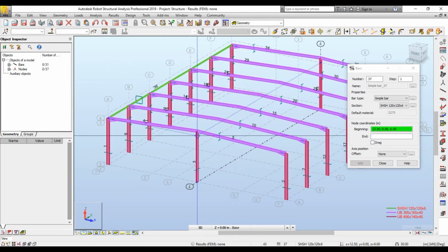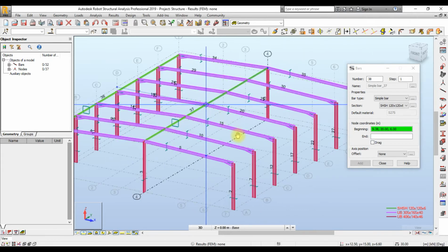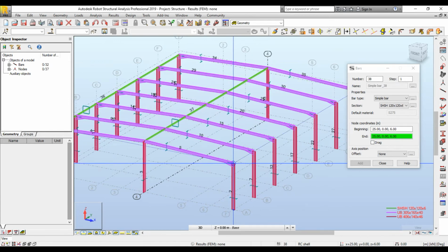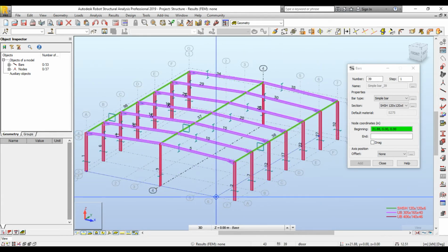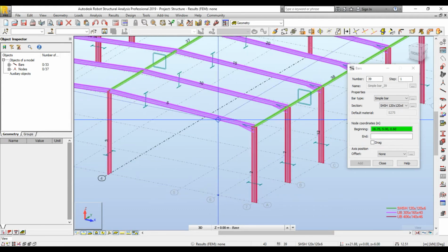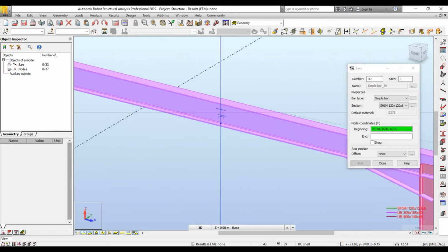Then I'll move from this guy here downwards. That is it. Then I'll also move from here downwards. This is another SHS. I'll also move downwards. And if you should notice, I created all these SHS earlier on, predefined. What I'll do now is come downwards here a little bit, to snap. I want to snap it to the center point of the bin, which is here.